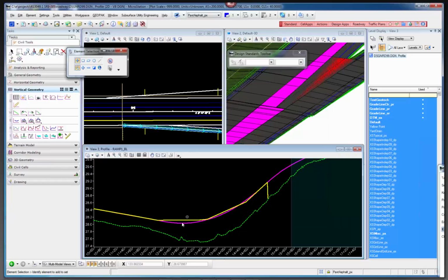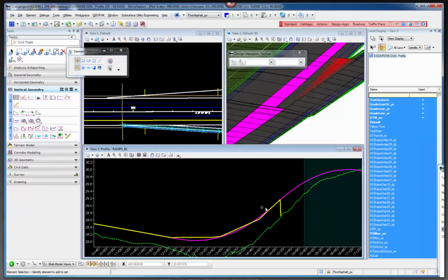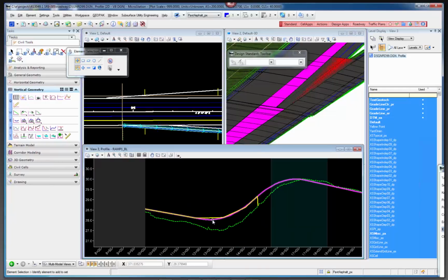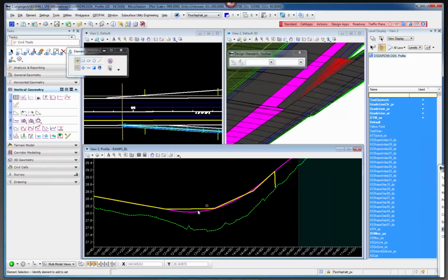And based on your interval, it's going to drop in this profile. There are times when these project profiles and profile by 3D elements will give you these little spikes. So this is the existing terrain, and this is what it's calculated from my main corridor using that one template. Once I have that, I can go in and establish a new profile. I can place a tangent here, place a tangent here, place a tangent however you want there, and approximate that profile of where it would be.